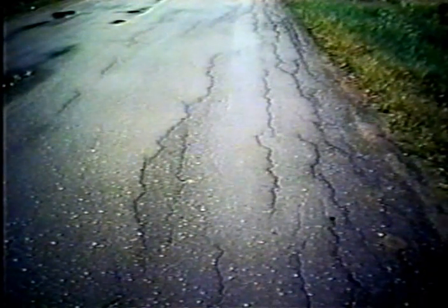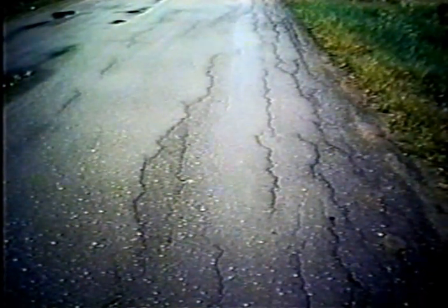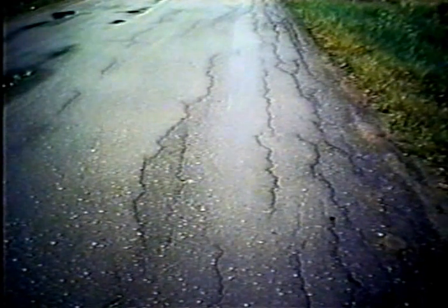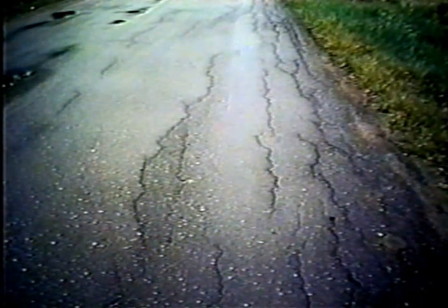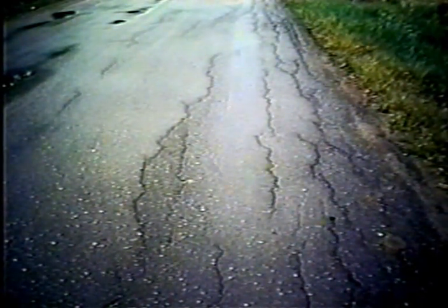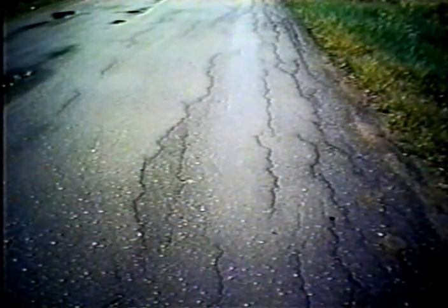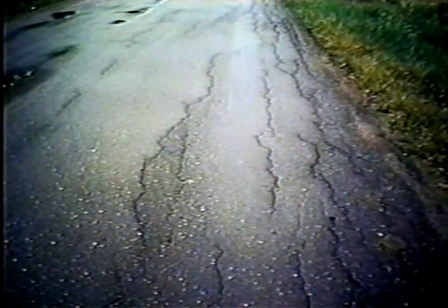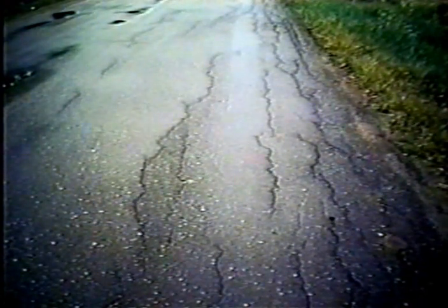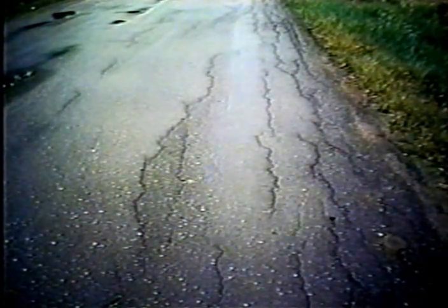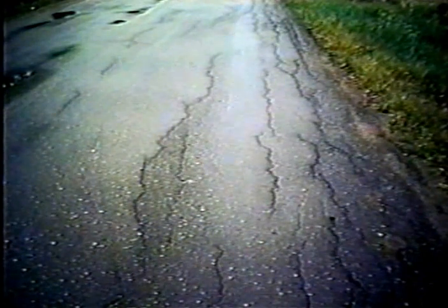Here's a good example of a recent overlay. If you look carefully, you can see some water collecting in the wheel paths, and you can see quite a bit of longitudinal cracking occurring from the center of the lane on out to the edge. To me, this is an example of selecting the wrong maintenance technique. I would bet you that if you could see this pavement before they overlaid it the year before, it had